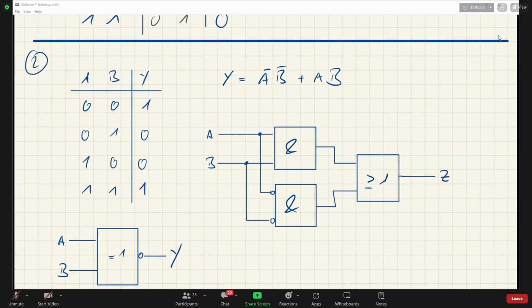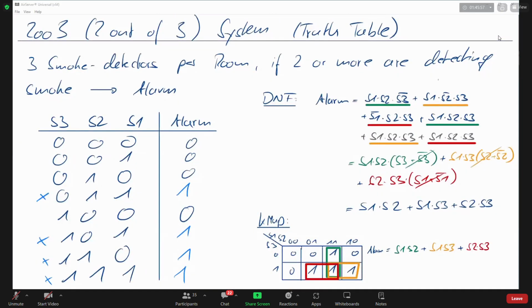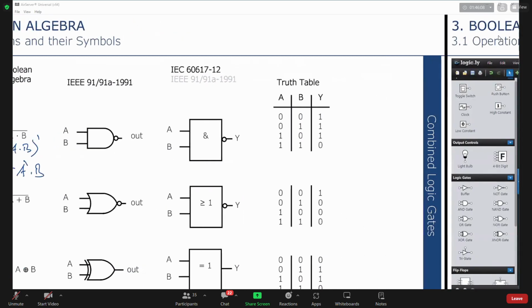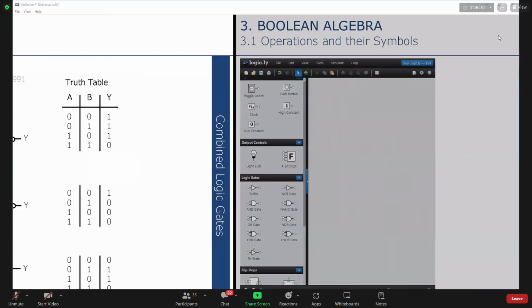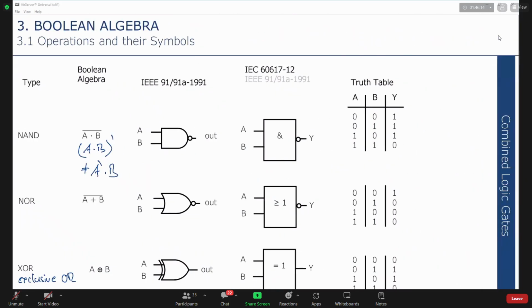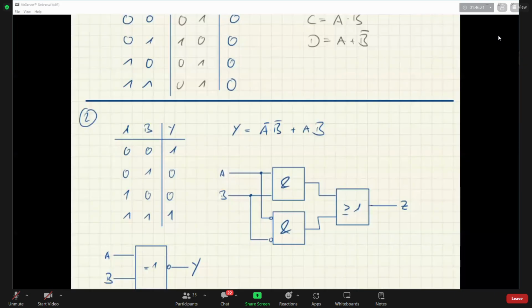It's like that. But if you're looking into the truth table of your XNOR, we never did the XOR. So, but that's the negated XOR. So here we have the XOR 0, 1, 1, 0. And here we have just the opposite of that, so 1, 0, 0, 1.